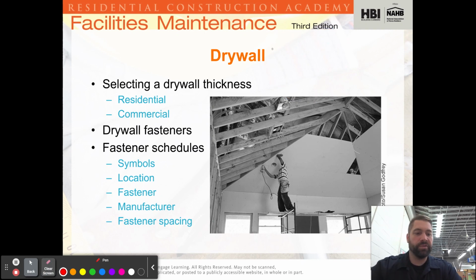Drywall fasteners, so you can use nails or you can use screws. In the lab, we will be using screws, and because we're using half-inch drywall, we're using inch and 5/8 screws.